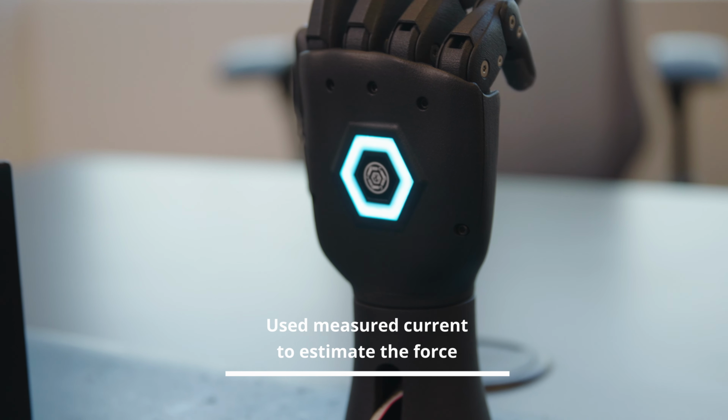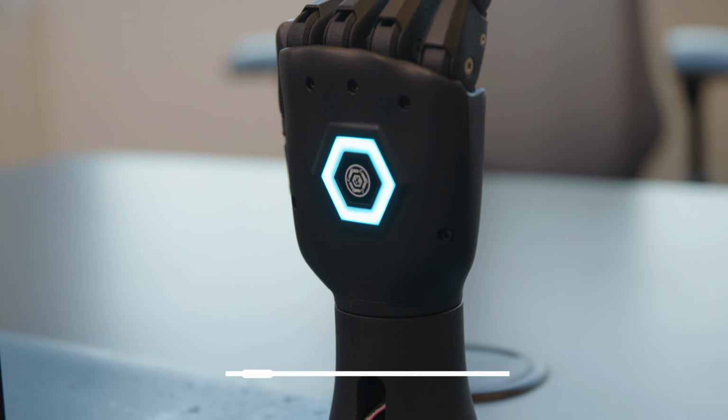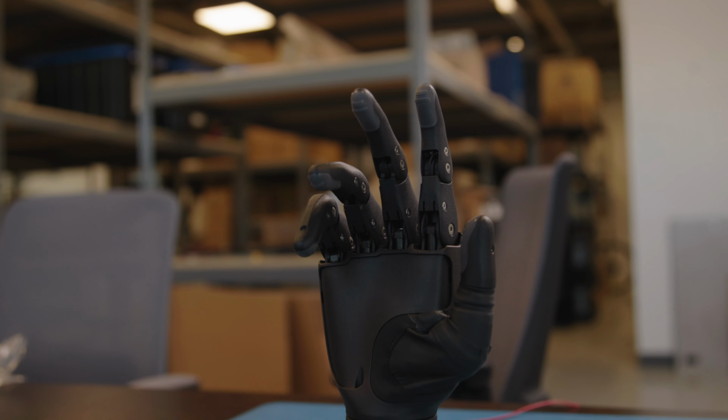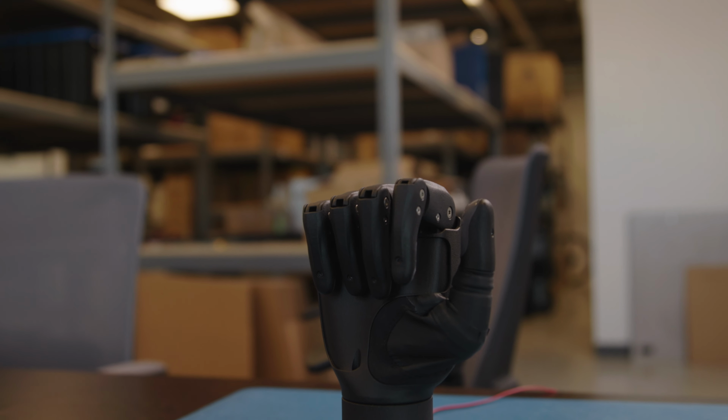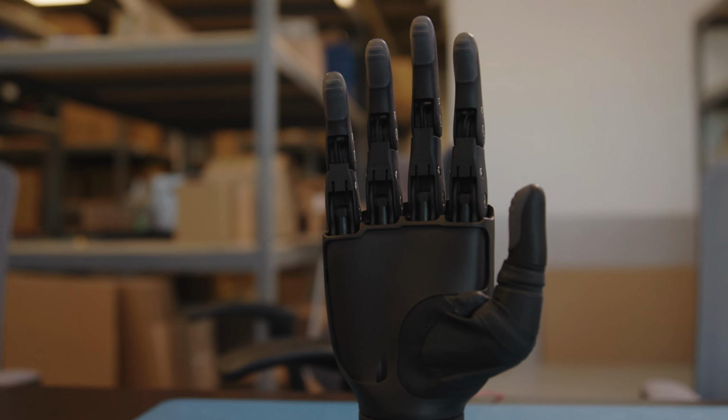Increasing the gear ratio can sometimes provide better life in some applications. If you measure the average current and force during the extend or retract movement, and you find it exceeds the peak efficiency point on the datasheet, repeat your testing with the next higher gear ratio option to potentially improve your cycle life.